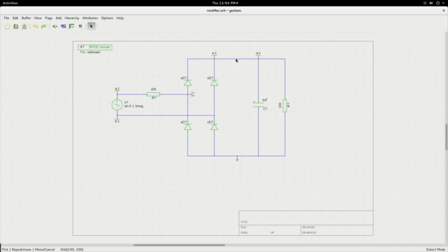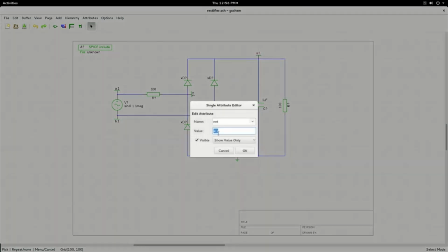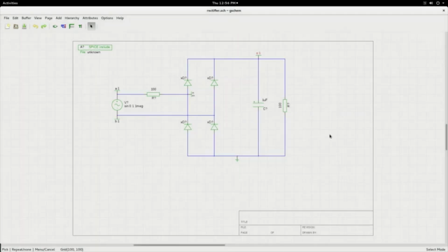I would like to place a track impedance here to introduce a non-ideality later on. So for now, I will just not give this label. I will remove this label and denote this label as O, so that we know it is an output label. So we have the labels, we have the ground, we have the components in place, we have wired it, we have to give the component names. So you double click on those.